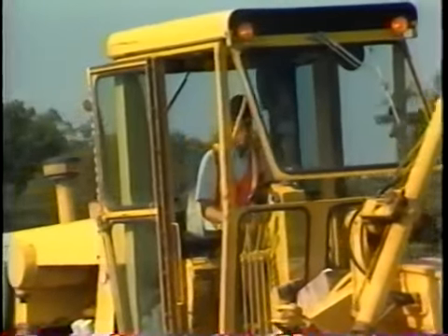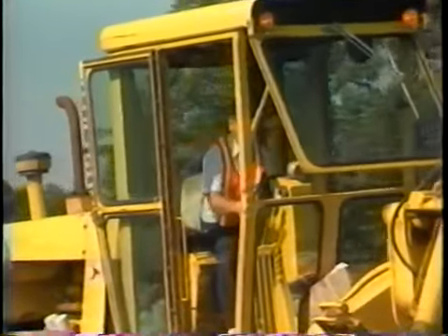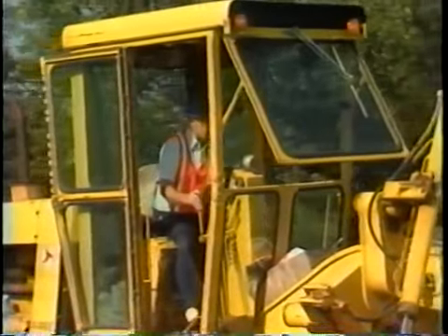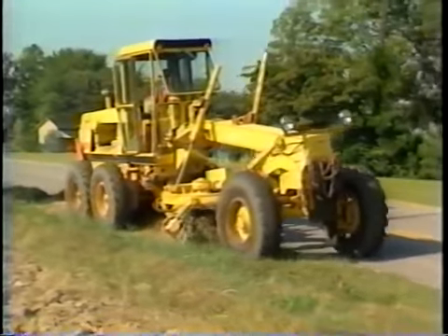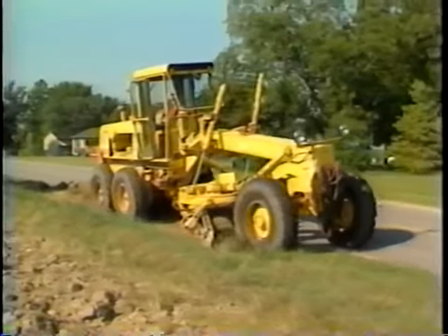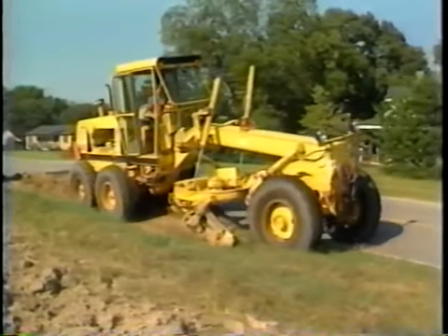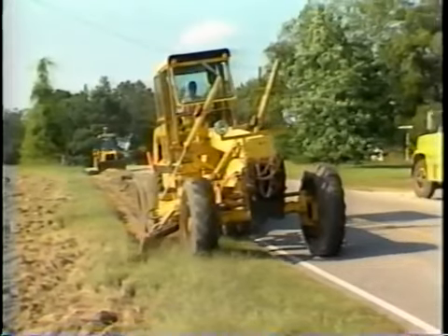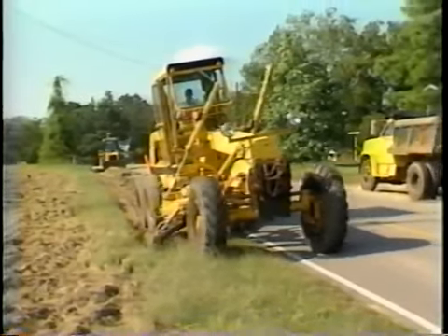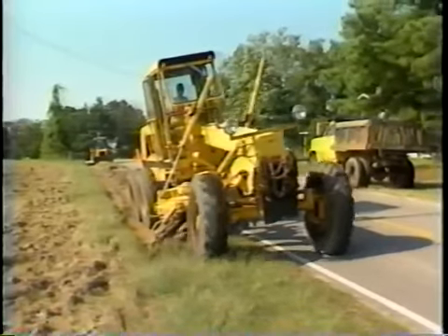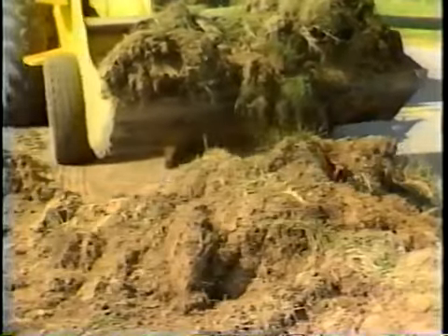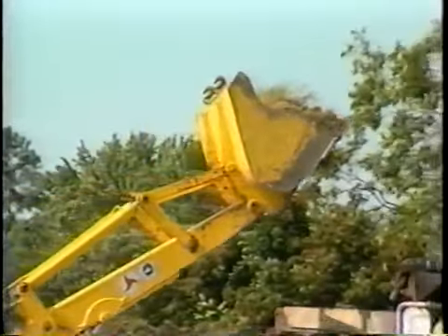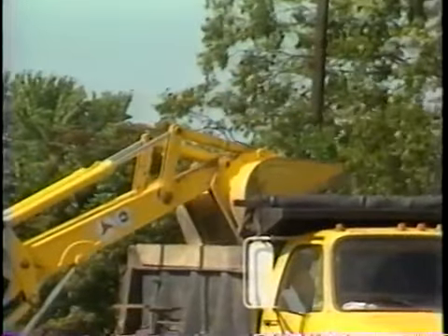The motor grader proceeds at no more than 3 to 5 miles per hour. This prevents the blade from bouncing and creating an unevenness in the shoulder. As the motor grader moves along, the blade cuts away the high spots of material and windrows it along the edge of the pavement. Cut the shoulder to the desired slope. Behind the motor grader, a front end loader picks up the windrowed material on the edge of the pavement. Load the material into dump trucks and haul it away to a waste area.